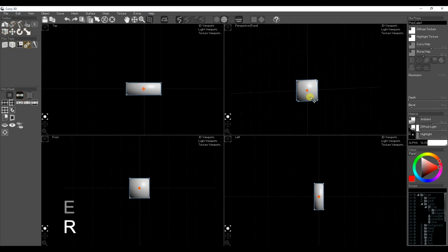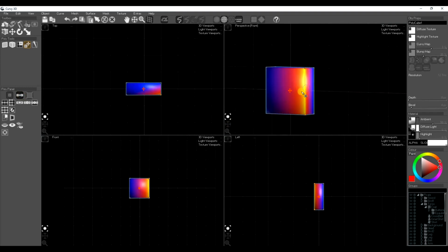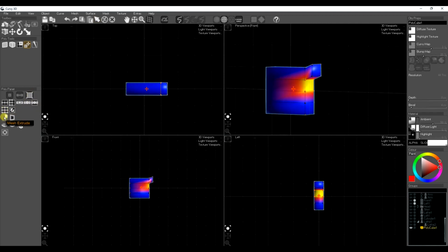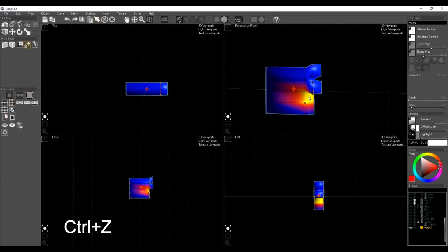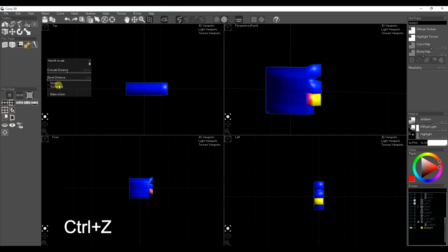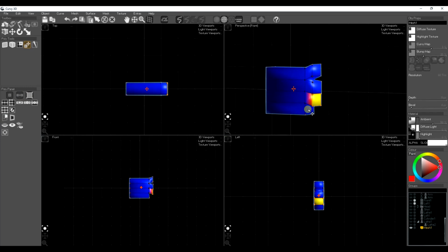Select one edge at the front of the object and use divide edge ring to add a loop of new edges crossing over with that edge. We want to split it into 4 chunks, basically to add for the 4 fingers. So we're going to individually select faces along the front of where the fingers are going to be. Select a finger base and then press extrude and bake until we've got 4 fingers extruded.